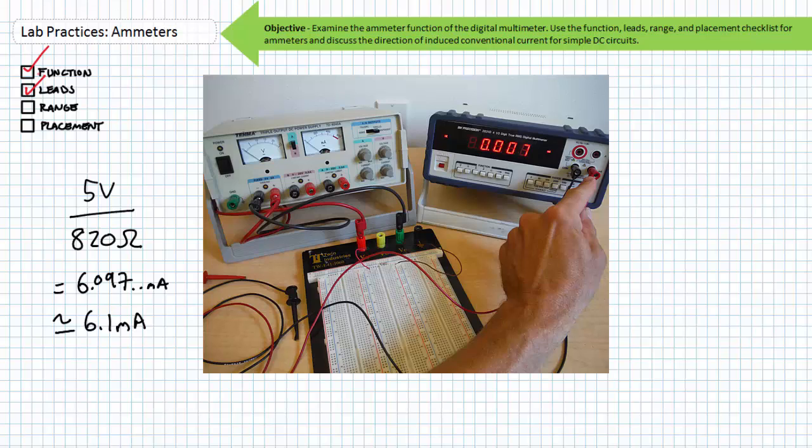There's a secondary input for large current measurements. Again, notice the DMM in ammeter mode is using different lead placement than our previous discussion of voltmeters and ohmmeters. The BK Precision, unlike the Fluke 87, will not tell you that the leads are in the wrong place for a given function and will sit quietly in the passenger seat as you drive your lab off a cliff. Don't get mad at the DMM when you're the one in the driver's seat.